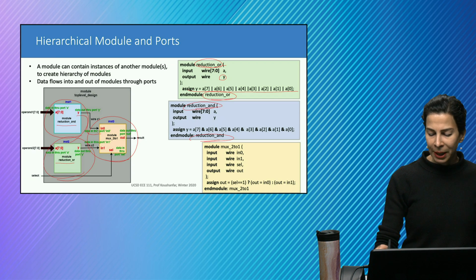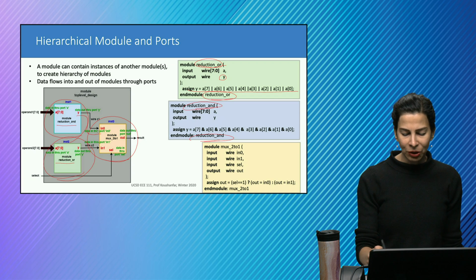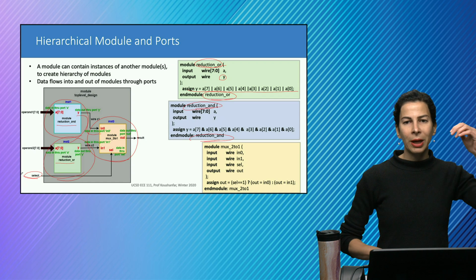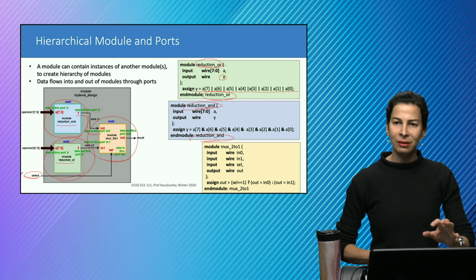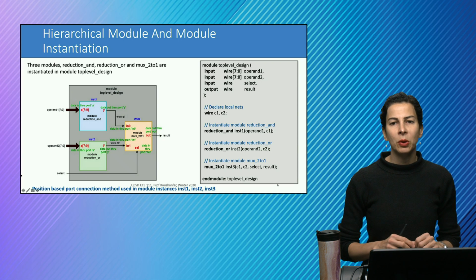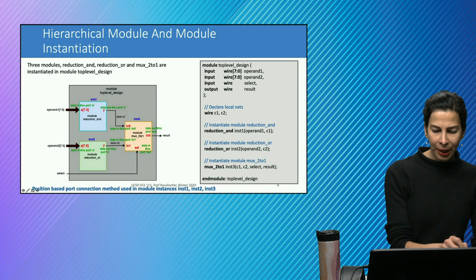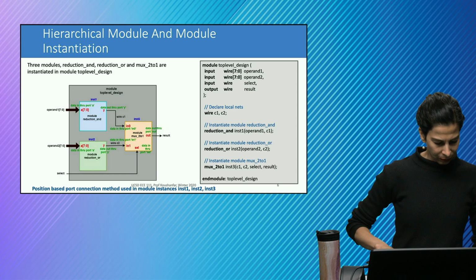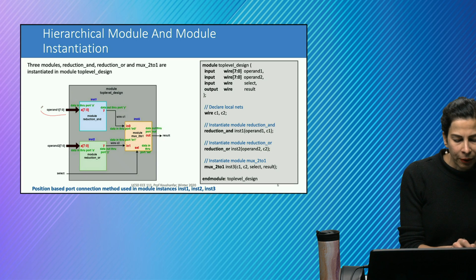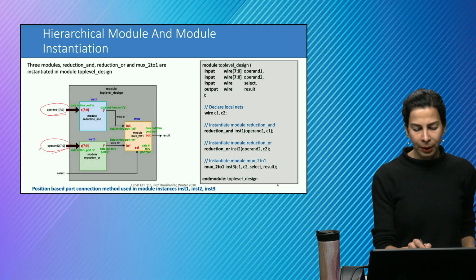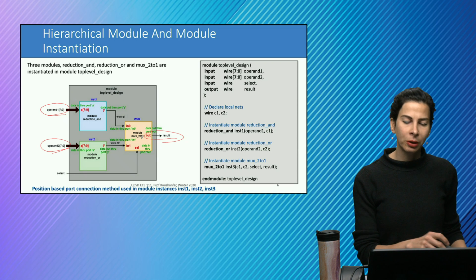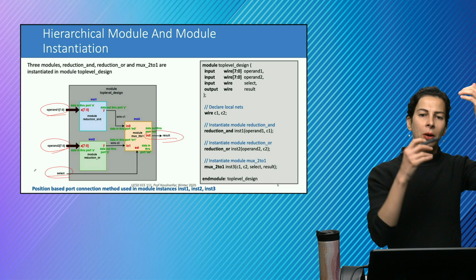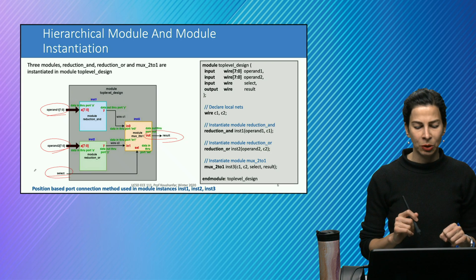On this particular page, we're just defining the MUX module itself, which is basically a selector between the two based on the select signal. Now, if I want to write a higher level design which contains these three modules, I'm going to define it with inputs to the big module, the result, which is the output of the big module, and a select signal. So I'm going to define that higher level module with those three interfaces that we just described.